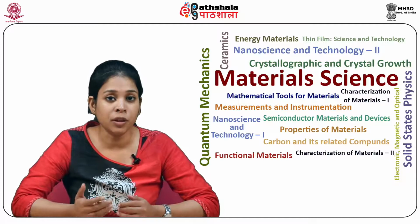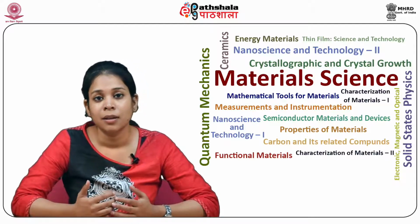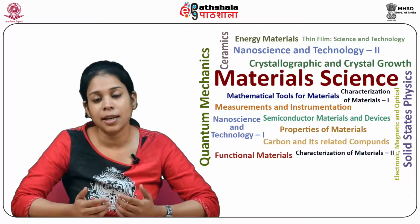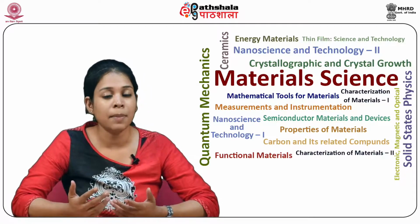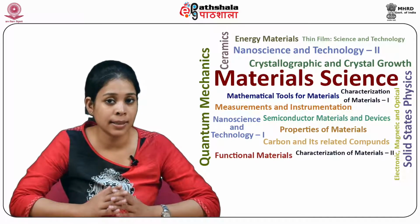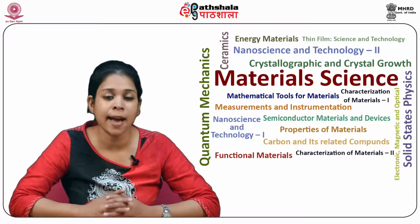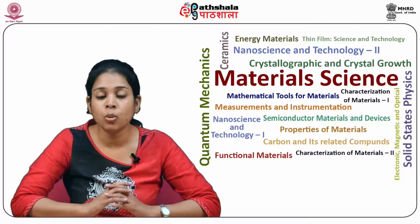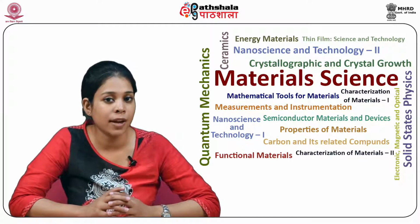This variation in composition is accommodated in vacancies in either the oxygen or titanium lattice sites. In stoichiometric TiO, only 15% of cation and anion sites are vacant, and hence this compound has an unusually high concentration of Schottky defects.